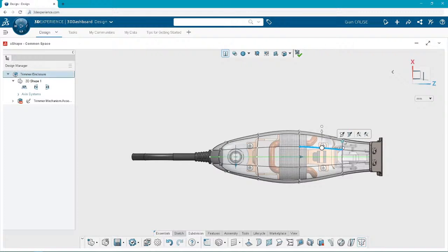All right, adding more loops. The more detail we add, the more control loops we need. So I'm just going to use the insert loops command, which also exists down below in the action bar, but you can click it right in our shortcuts as well to quickly go from making adjustments to adding that